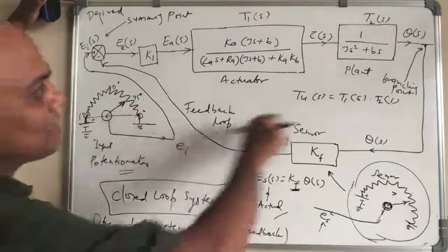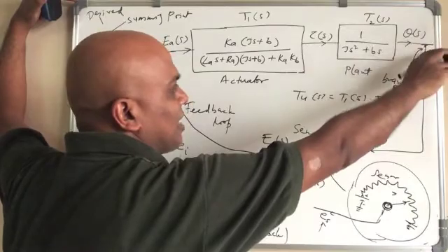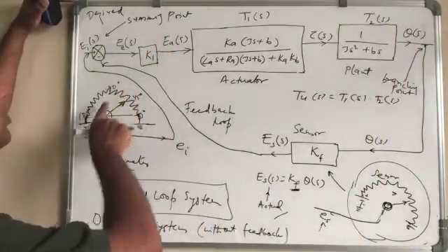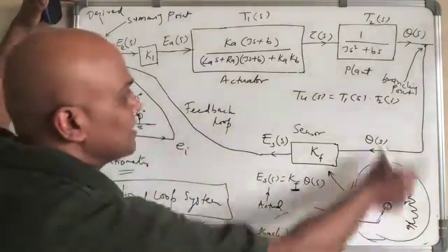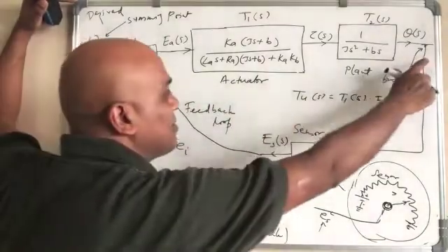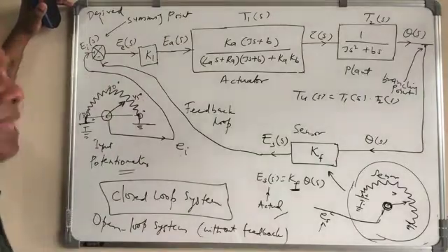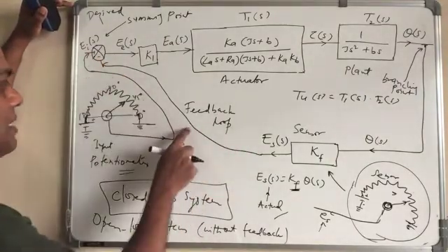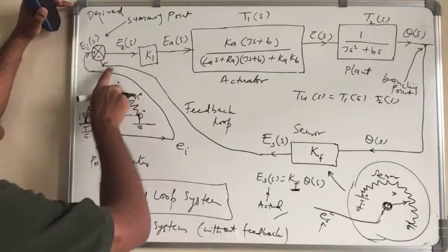Here, let us say the original state right now is 35 degrees and you want 45 degrees. If here is 45 degrees and here is 45 degrees, you get exactly the same voltage from both of them. Since this is subtracted from this one, you have plus here and minus here, so it will be 0.